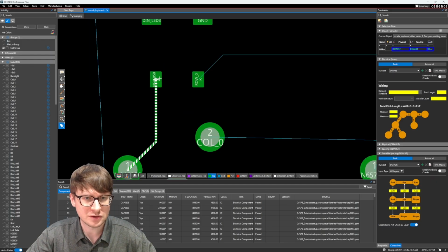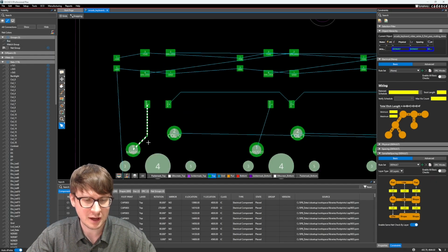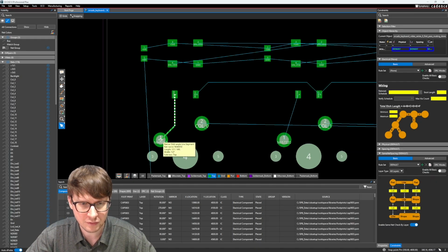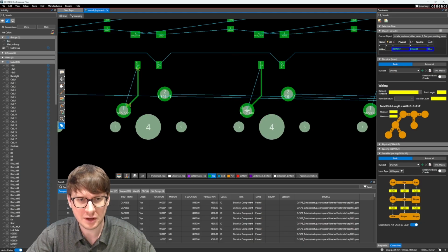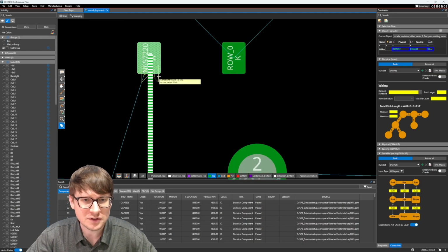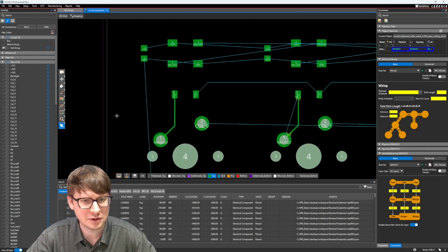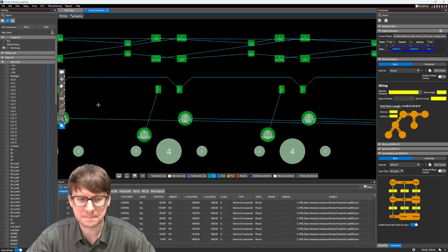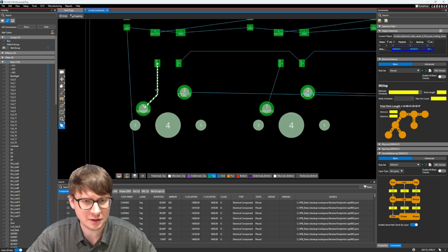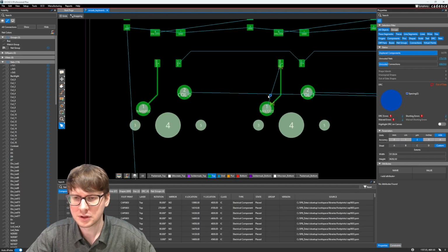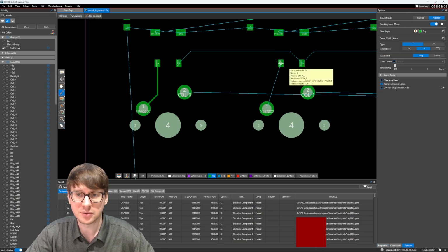I will hover my mouse over the center of, let's say, this pin here, copy, and then I should be able to, oops, that didn't work. Let's try that again. There we go, copy, paste. And what is this complaining about? Line to SMD pin spacing. Not on a net. All right, let's just go ahead and, well, no, this should work. Let's figure out why it's not working. All right, let's just go ahead and do this manually.